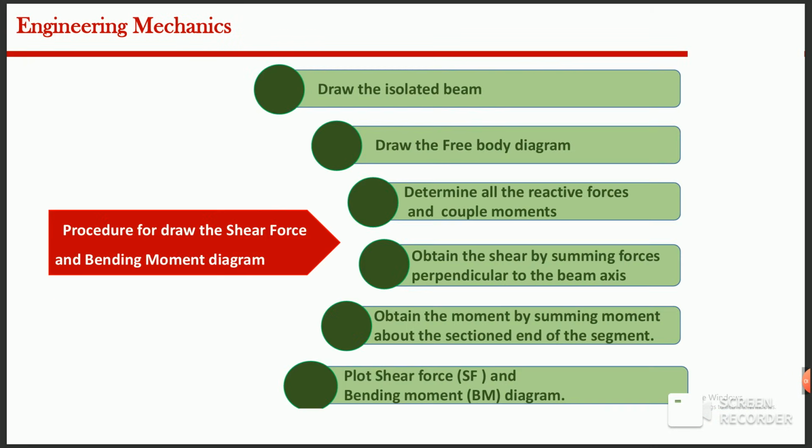Before solving any problem, we must follow a systematic procedure. The first step is to draw the isolated beam by separating it from its supports. Then determine all the reaction forces and reaction moments acting at the supports. Then draw the complete free body diagram showing every external load and support reaction.